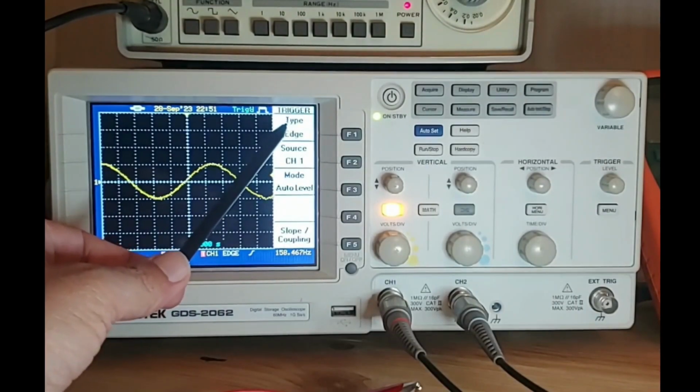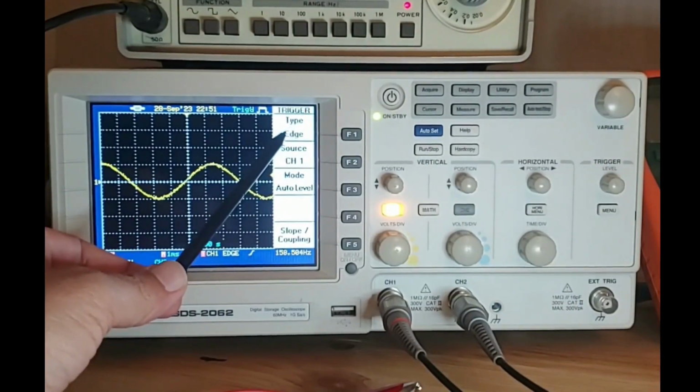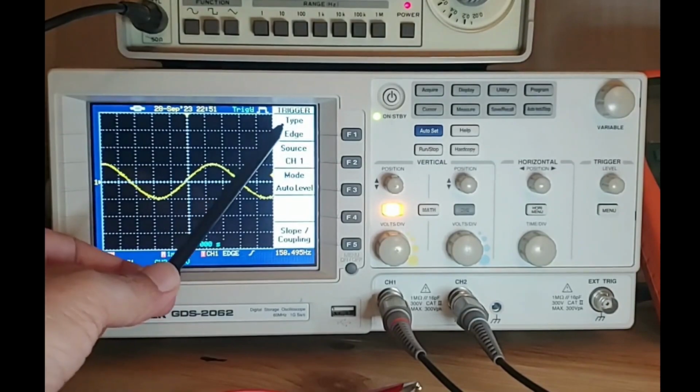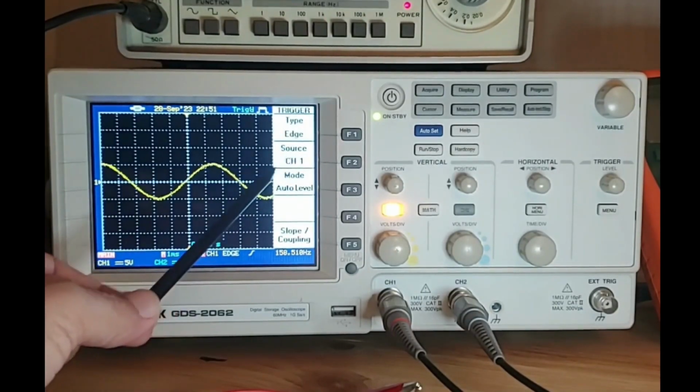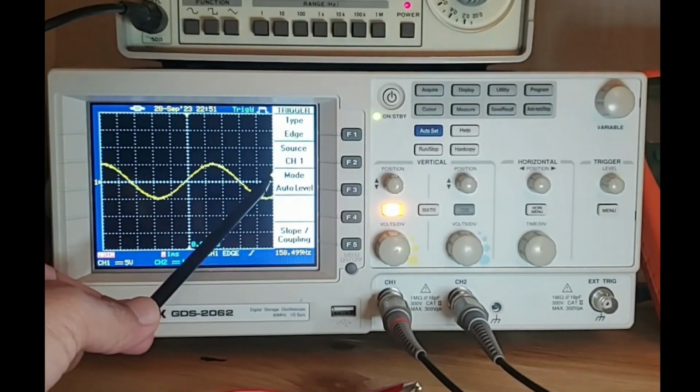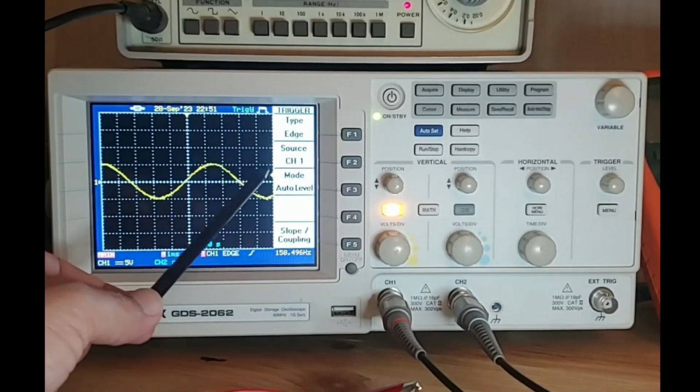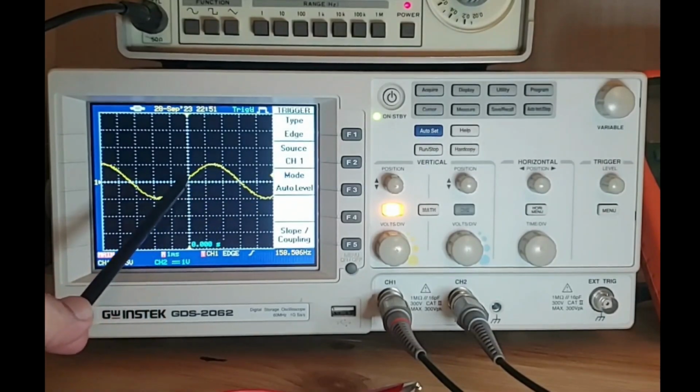Right now, it says that the trigger type is edge. So what it means is that the oscilloscope will look for a rising edge or a falling edge of the voltage waveform to trigger the trace, which will start plotting the trace. The source of the trigger is currently channel 1. As you can see, this arrow over here is the trigger level. So when the voltage of the waveform approaches this level, then the oscilloscope will start plotting. And you can see here that the oscilloscope starts plotting here.